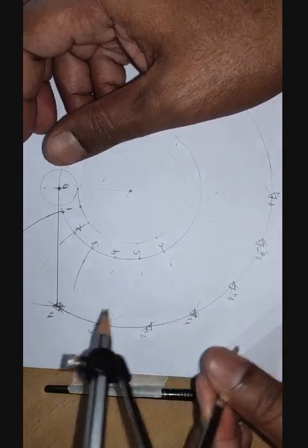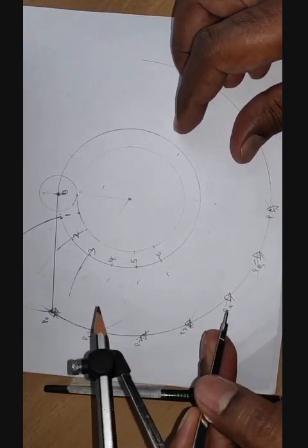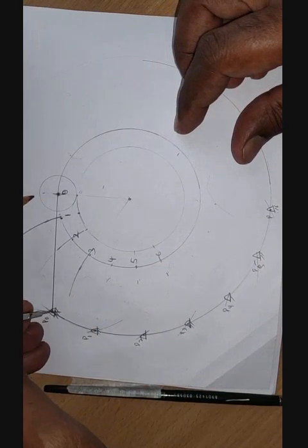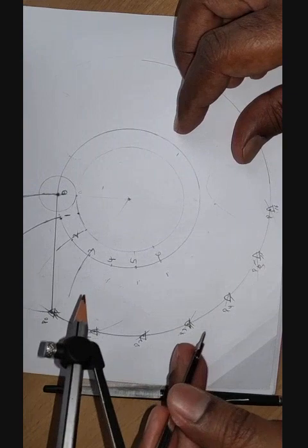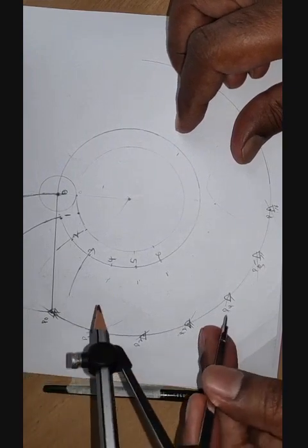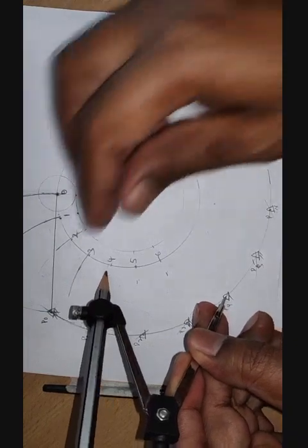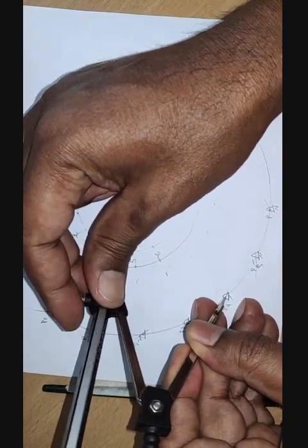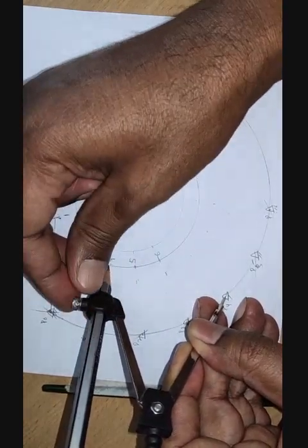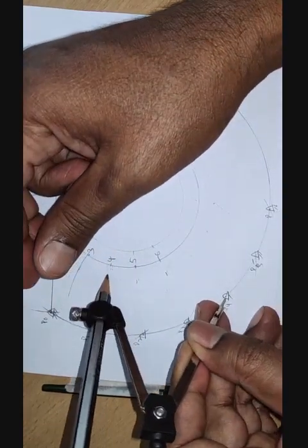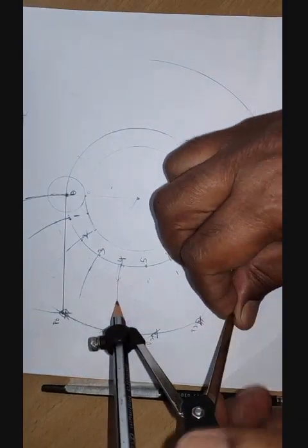So you draw this arc so that you can locate the position of the rollers as it rises, because the way it can go up and down is along this arc, and therefore you have to draw this arc to locate this. Of course, here you should keep this as this. I mean this is equal to the lever length, but here I'm trying to adjust this because the accuracy is not a big issue, but you should know the procedure.